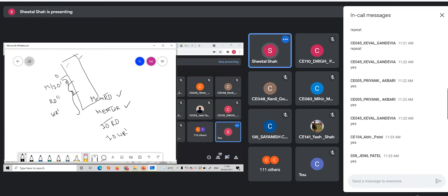Suppose M/IO bar is 0, read bar is 0 and write bar is 1, because read and write cannot be done at the same time. What would be the output at pin number 0? If I want to select memory, M/IO should be 1. If it is IO, it should be 0. So it would be IO.